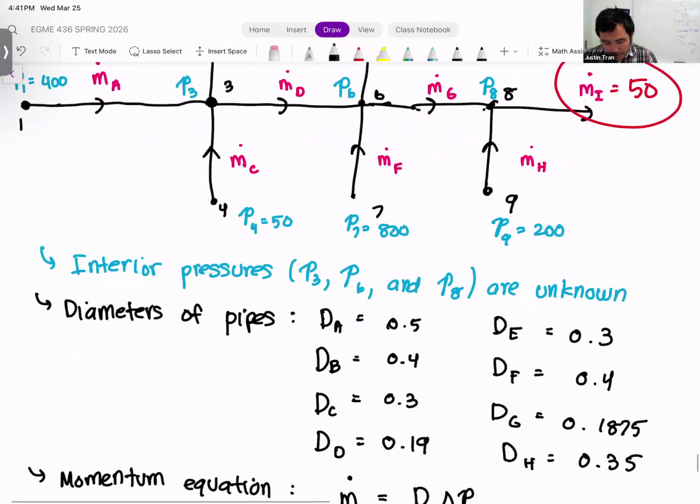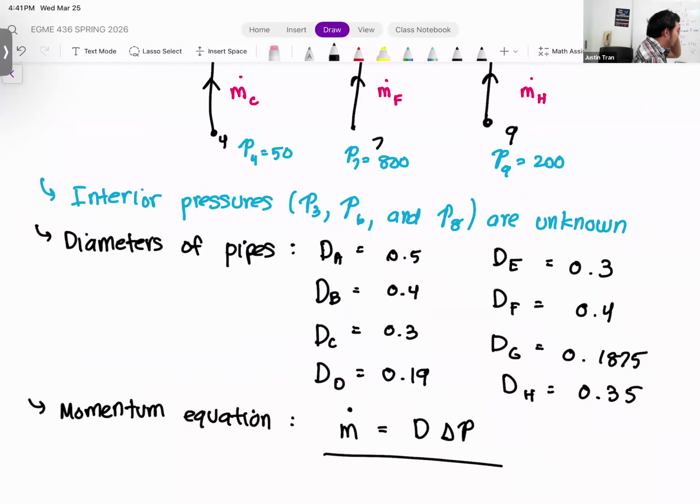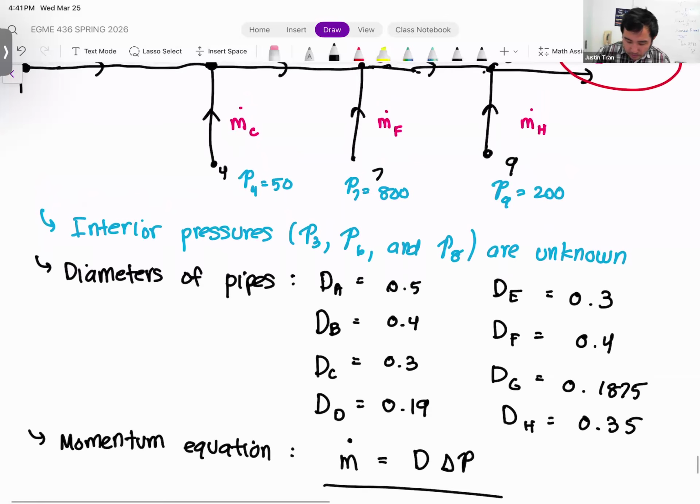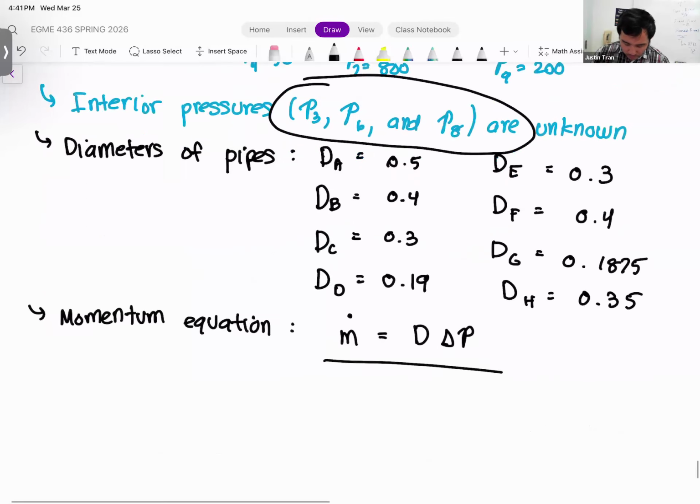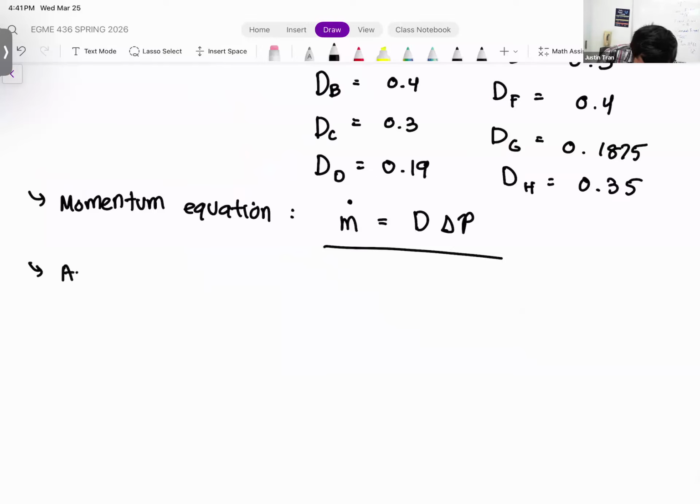Okay. So a lot is set up for the problem, right? But I promise the problem itself is more straightforward. There's just a lot of numbers for this problem. All right, so let's go ahead and apply our simple algorithm to basically solve for these pressures here. And then along the way, we're also going to solve for the mass flow rates as well. Apply SIMPLE. All right, so let's go through our steps of the SIMPLE algorithm and let's see how they apply here.